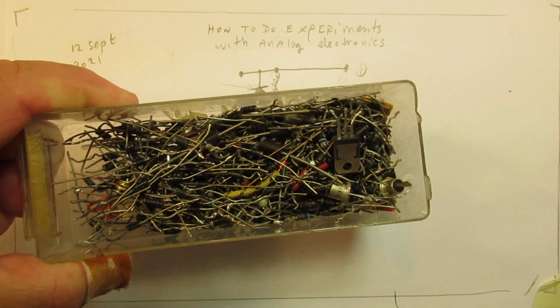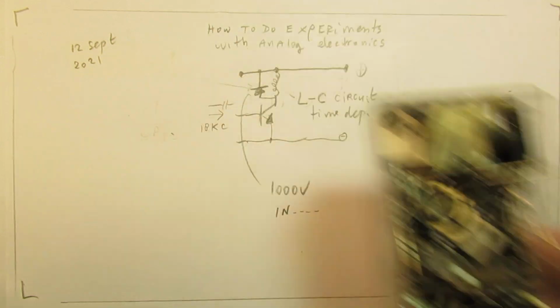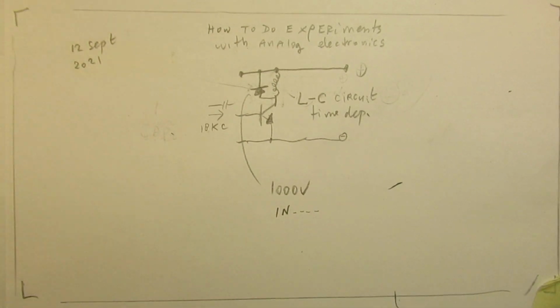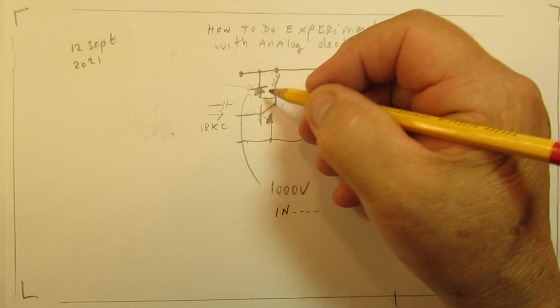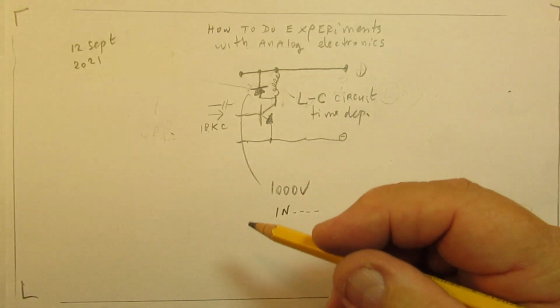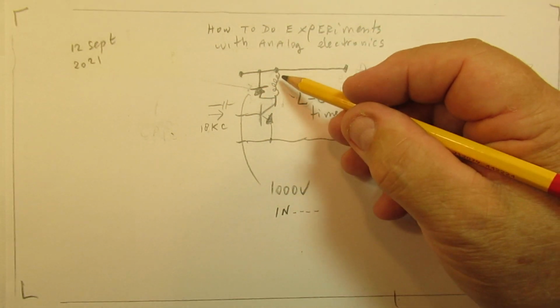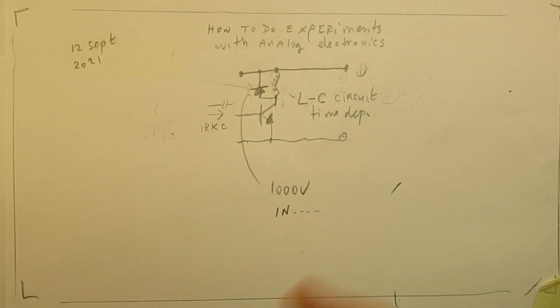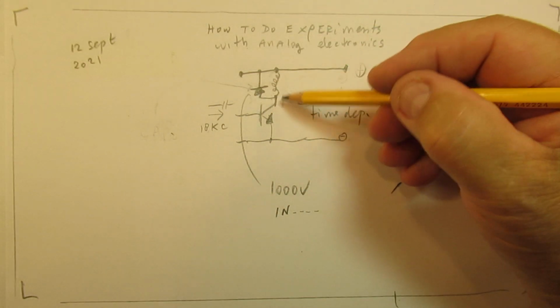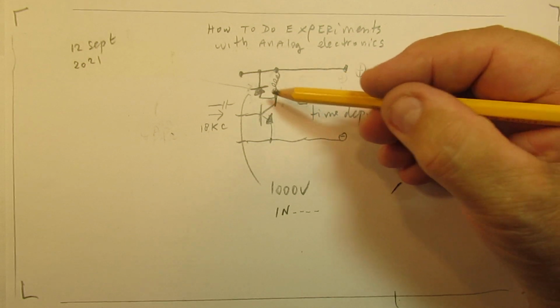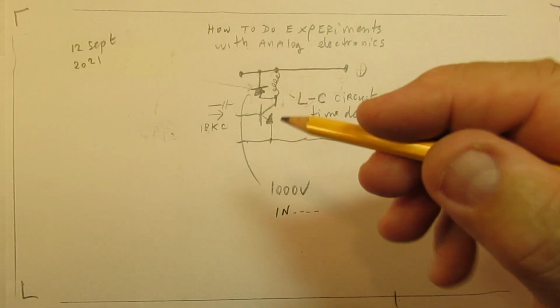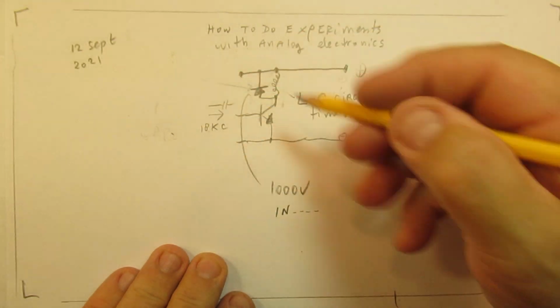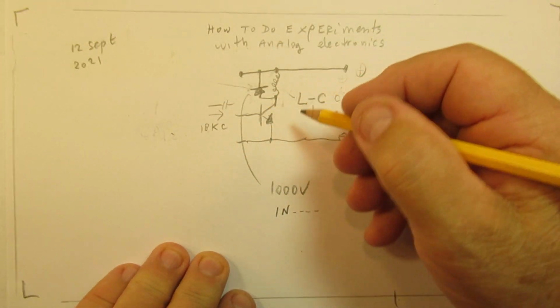Many of them can handle 1000 volts, and here power diodes. So that's a quite good solution, but in many cases you can use that resistor instead of the diode. And the good thing of a resistor is that it is not frequency dependent. So it could help. You can get that coil into oscillation, preventing it from damaging the transistor, etc., etc.